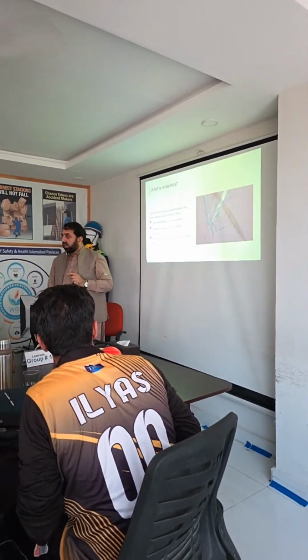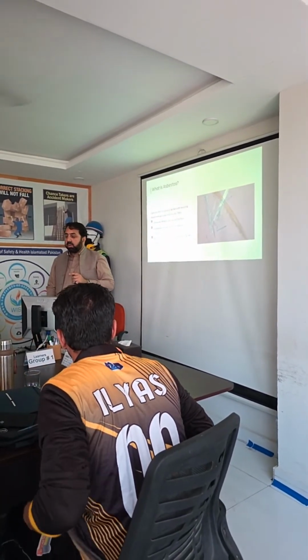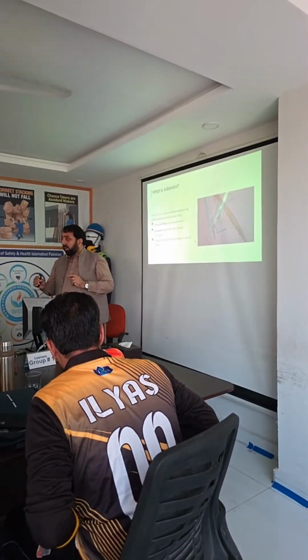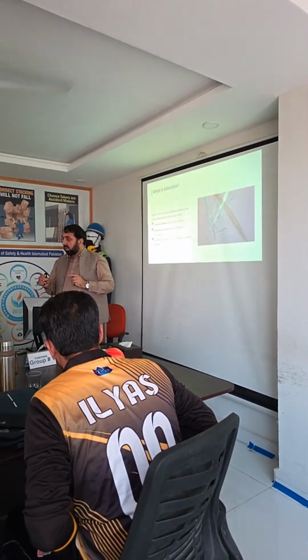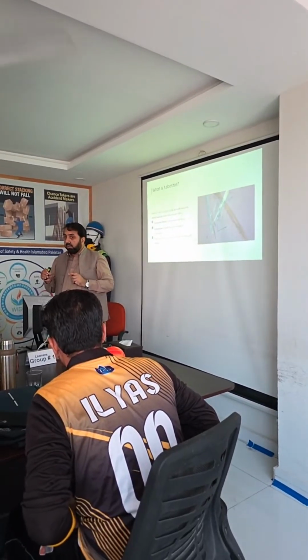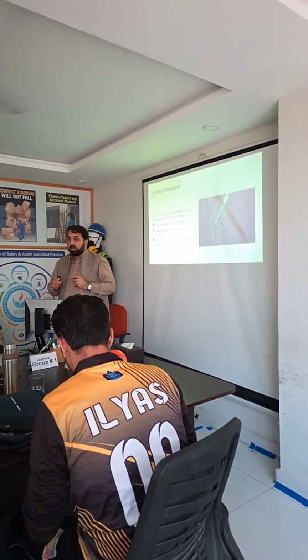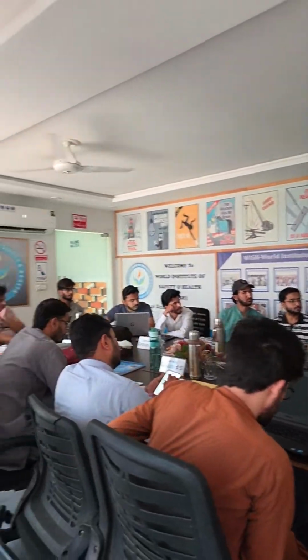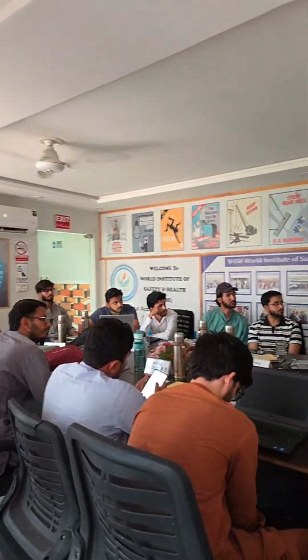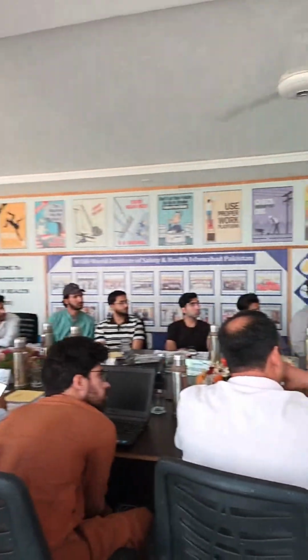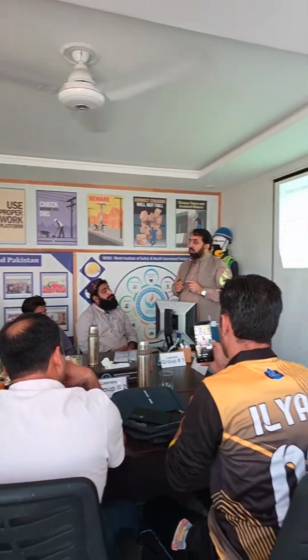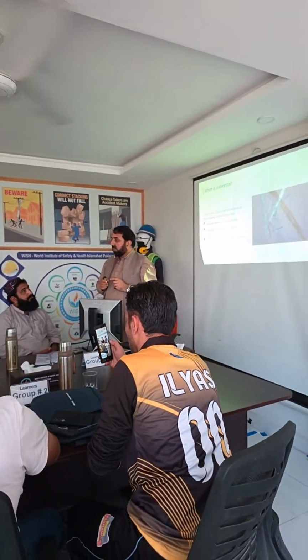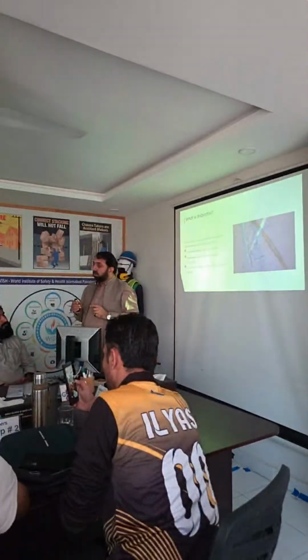If asbestos is there in your workplace, you must check for ACM. What is meant by ACM? Asbestos containing materials. If the ACM is there, you must take proper preventive measures first, because exposure cannot be seen by the naked eye. Mostly asbestos fibers are needle-shaped in the air, not visible to the naked eye. And most people affected by asbestos fibers suffer chronic effects. They don't know about it.